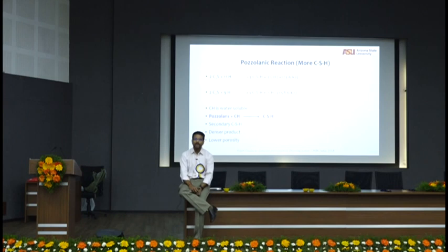Right. So if you don't have enough fly ash, if you don't have enough calcium hydroxide, do you know roughly how much calcium hydroxide, as a percentage of the total volume, will require no more fly ash to be added? Depends on silica and alumina content of fly ash, right? Now fly ash also reacts starting from the surface. If any of you have done this research, have you done a 30% fly ash or a 40% fly ash, and at 90 days have you gotten a system with no calcium hydroxide remaining?